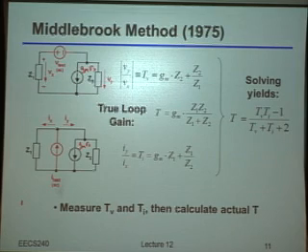All right? So in particular, what he did was the following. He said, well, if this was my controlled current source here, let me first break the loop by inserting a voltage source, this V-test. And what I will measure is, when I apply this V-test, the ratio between the output voltage Vy and the input voltage Vx. And again, I can measure that totally in SPICE.